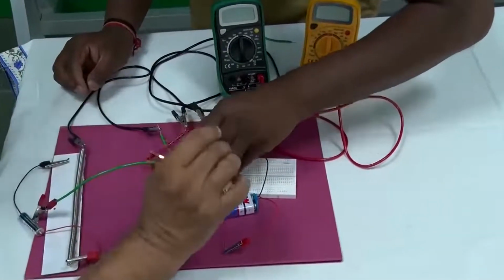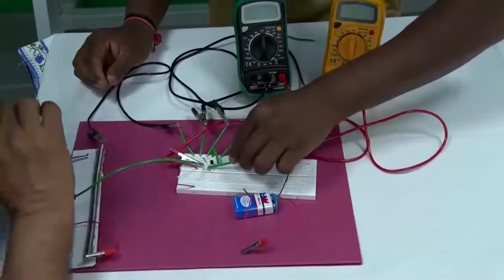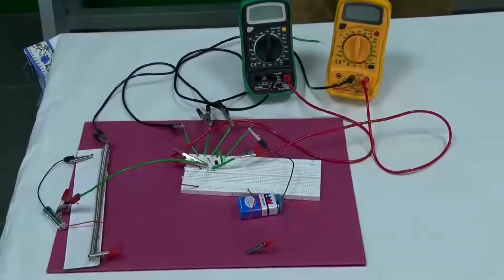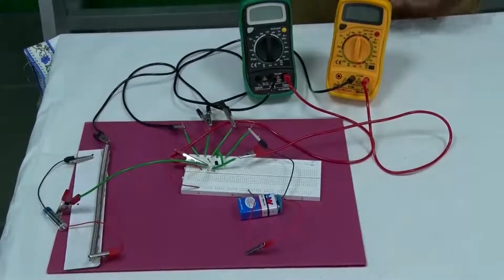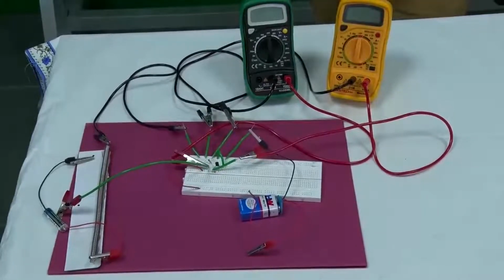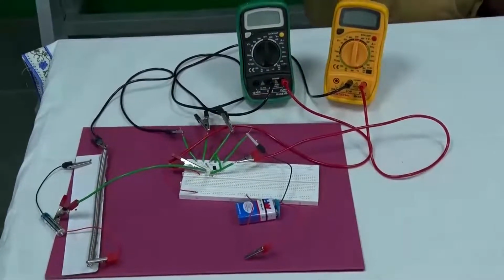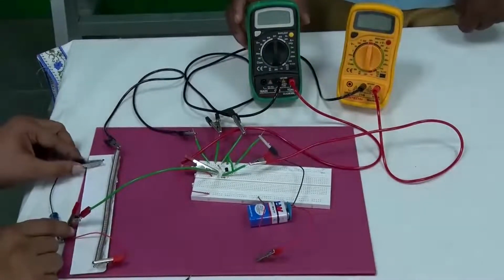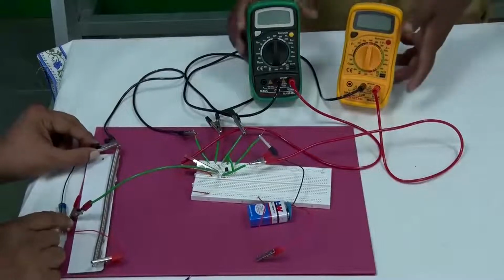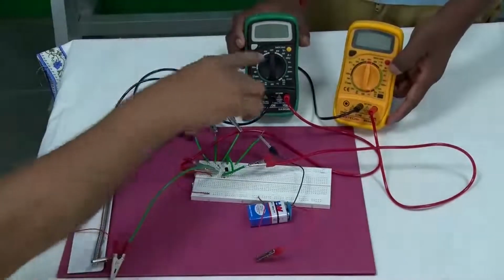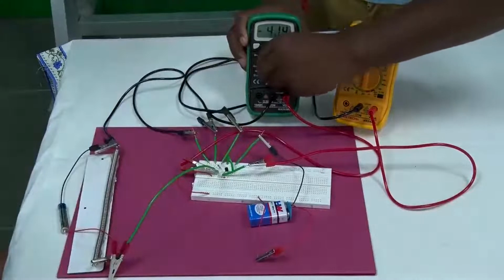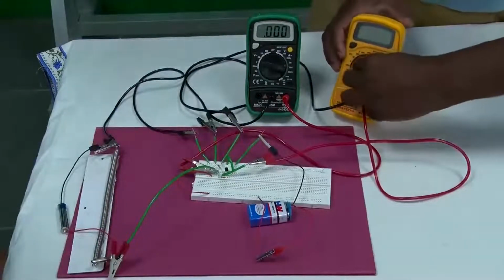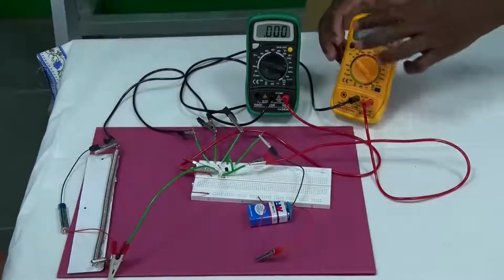And you can connect this thing here, right. So, now it is connected to the collector. Okay. So, the circuit is complete. So, let us start working on this. This 1.5 volt battery I am now connecting, all right, and put this in DC voltage 2 volts range, and the other one, output, 20 volts range.